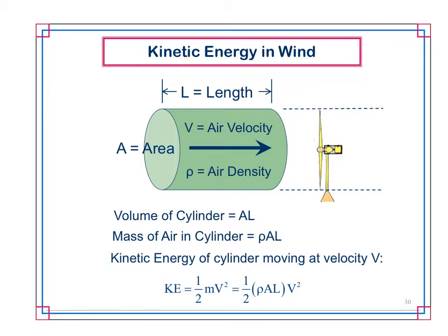So essentially what I'm saying is you can calculate what your expected capacity factor is going to be for a wind farm, okay? So a wind farm that is designed to put out 10 megawatts, you can calculate what you expect the capacity factor is going to be. Once you have that capacity factor, then you can calculate how many megawatt hours you're going to produce, and then you can take your fixed costs and your variable costs, add those together, and then you can figure out what you need to charge for a kilowatt hour, and then can you make money or not. Very simple, not very simple, straightforward calculation, but that's how you would come up with some cost estimates, because you've got to be able to pay your plant back.